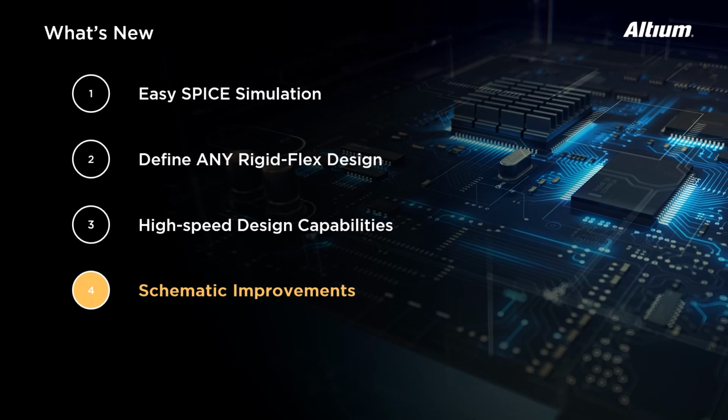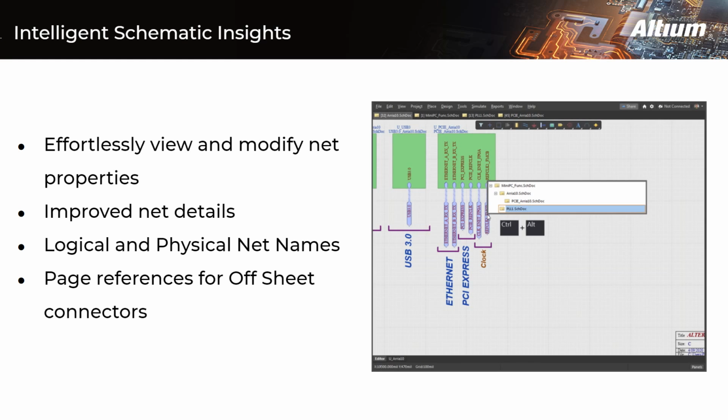We began changes to the schematic editor in Altium Designer 20. We can briefly go over the most impactful changes for this release. New and improved tools simplify the task of analyzing the connectivity in a schematic project. The Altium Designer Connectivity Insight functionality displays an instant view of the connection relationships within a PCB design project. Shown as a document tree with optional schematic previews, the selectable elements provide a quick and visual way to navigate through a project's connectivity structure.